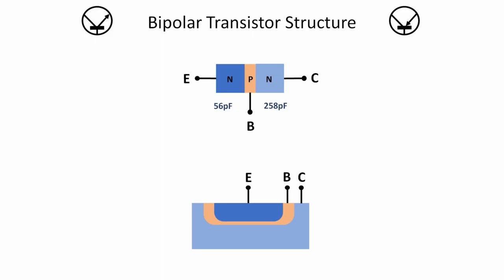We're just seeing it in 2 there, and my interpretation of those differences in capacitance quite simply is there's a much larger area between base and collector, which would result in a larger capacitance. That's maybe not the whole story, but that certainly for me is a useful explanation.